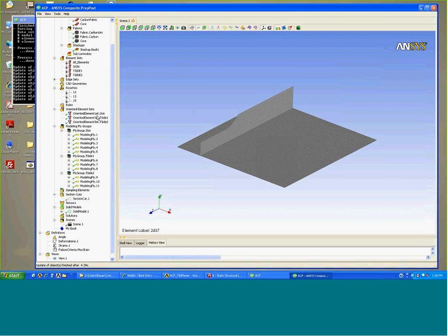Performing the draping with an oriented element set allows you to essentially define any ply being applied with the oriented element set to be draped over that specific surface. So it performs the draping simulation to calculate those ply angles. In this case, let me just show a simple example of draping on this particular T section and look at the resultant angles of the draping simulation.